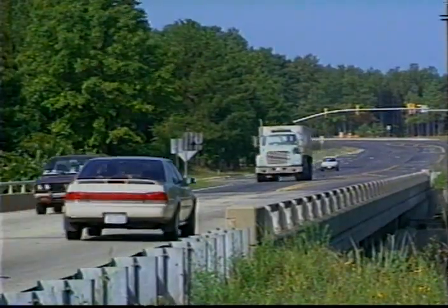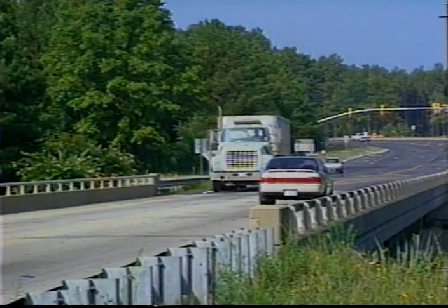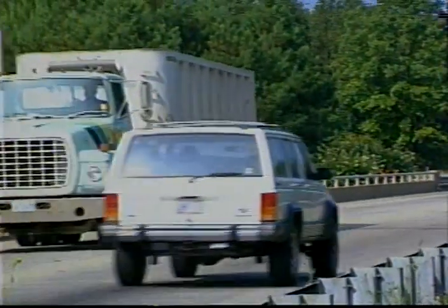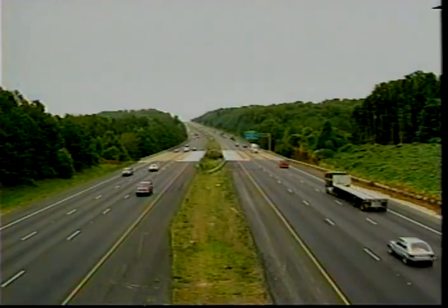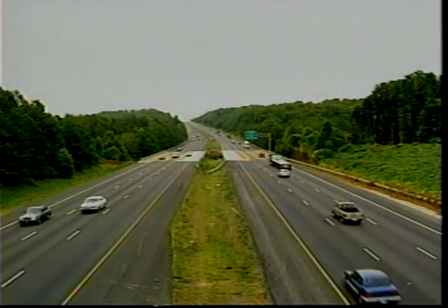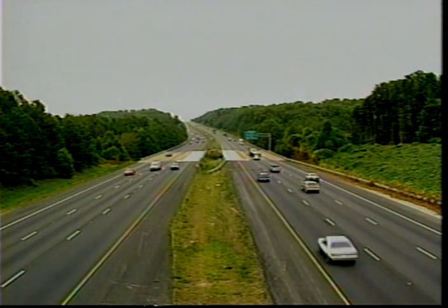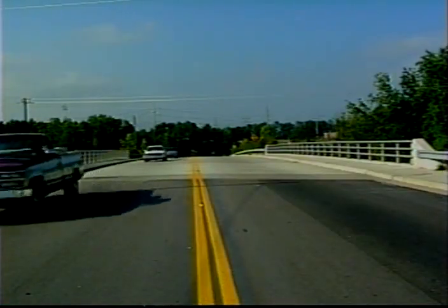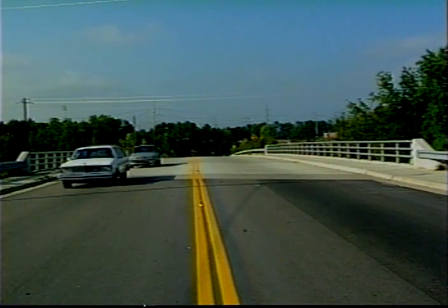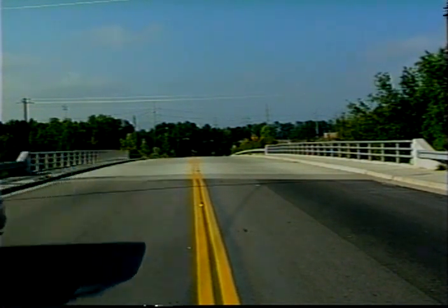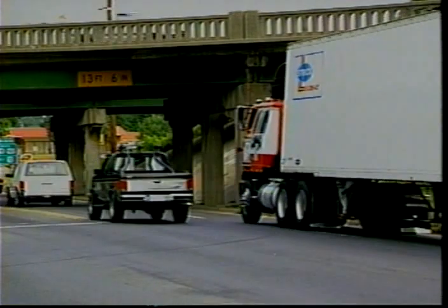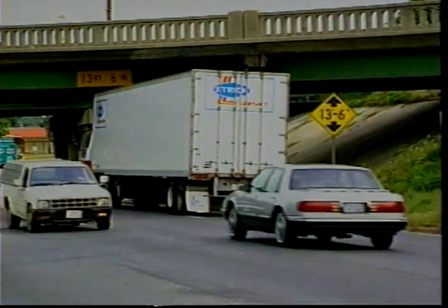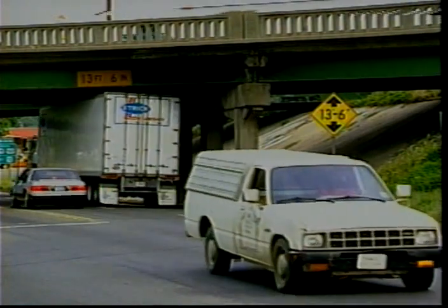The structural appraisal evaluates the overall strength of a bridge in relation to the class of roadway served. The approach roadway appraisal evaluates how closely the roadway at the bridge is aligned with the general roadway the bridge serves. The deck geometry appraisal determines how adequate a bridge roadway is for current traffic demands. The vertical and horizontal clearance appraisal indicates adequacy for vehicles using a bridge or passing under a bridge.